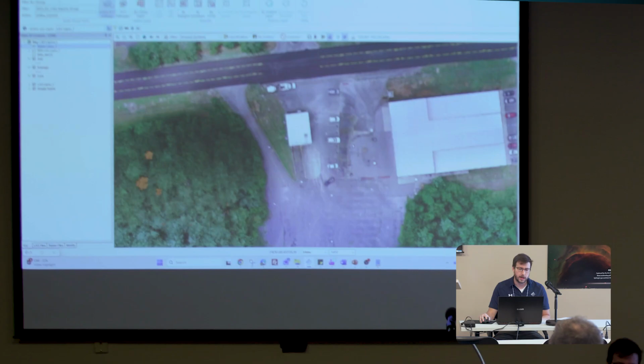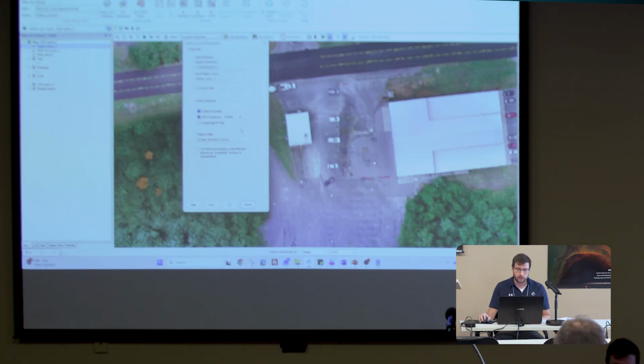Once you've selected that, click on Active PCT Settings. One of the things we have in here, I was playing with this last night. Yours should be set to something like 60. We have the ability to perform some additional JPEG compression on the data to make the file size substantially smaller, but the quality is very similar to the initial file. And also we can update the pyramids. If you're bringing this into CAD software, you will uncheck the Create Big TIFF option. That's important. We're converting from this Big TIFF file to a file that's just regular TIFF format.